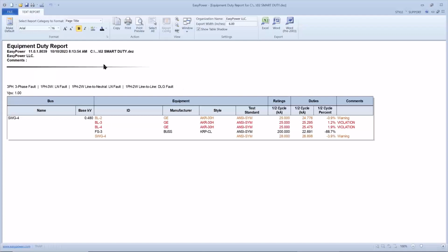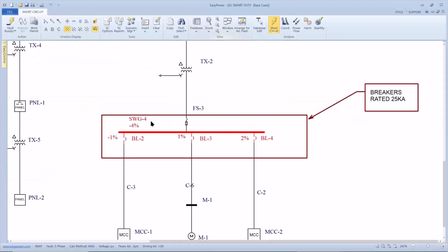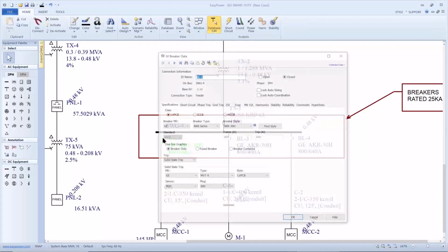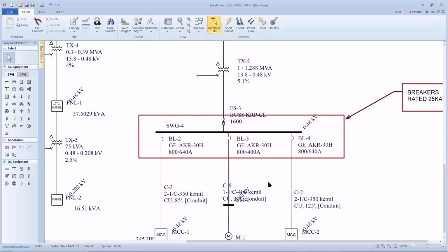Okay, I think you're talking about my salting the equation. So let's go back. I think the question he's asking is correct, and that is, if we've properly set these parts up for auto calculation, will it work? And the answer is yes. So if I auto calculate, I see that device library tells me this part's actually rated for 42,000 amps. Again, I kind of salted this example to show off the advantage.